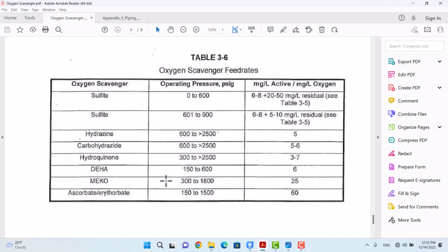Of course, that is why we use the other chemical for the high pressure steam. We have two steam drums: one of them is a low pressure steam drum, and another is a high pressure steam drum. For the low pressure drum, no problem is going to happen, because according to this document, it is suitable for low pressure steam drums. But how about high pressure steam drums? The reason we used it for high pressure steam drums is that we have seen experiences in other plants where it had been used for high pressure steam drums with no problems.